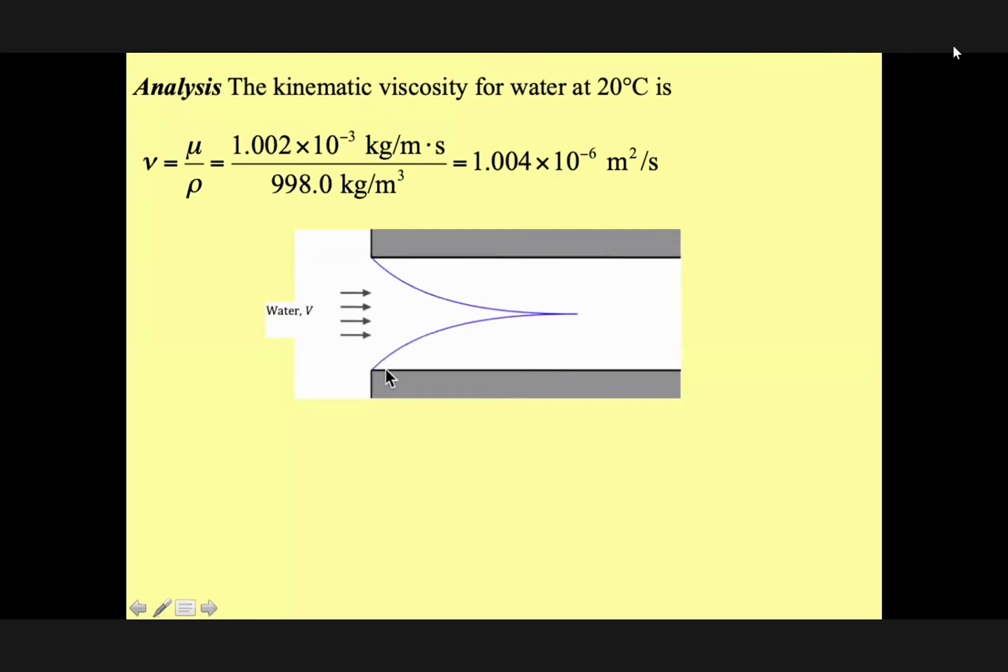And this is the problem. If you look at this plate, the velocity profile grows. If this is not there, this will go up right here. As x increases, this velocity profile increases like this. If I ignore this one and look at the upper one, this velocity profile also increases. But since this is symmetric, the same material, the same roughness, the same temperature, both are developing simultaneously together. They reach a point where this velocity would like to go here, and this velocity wants to go here, but since the forces are equal, they agree together to go like this.